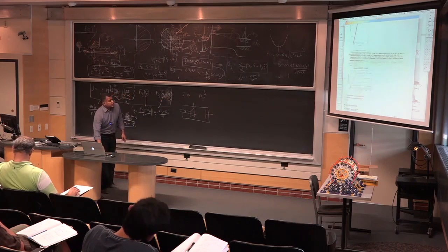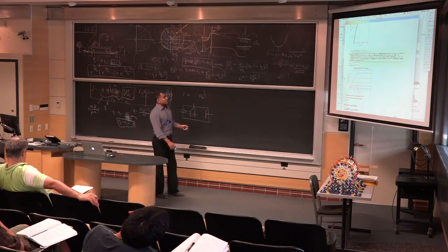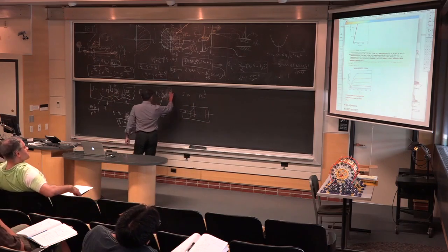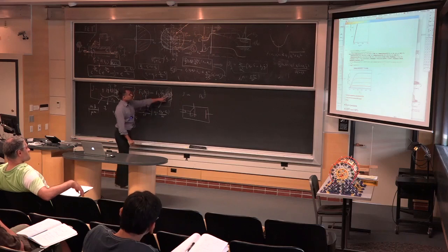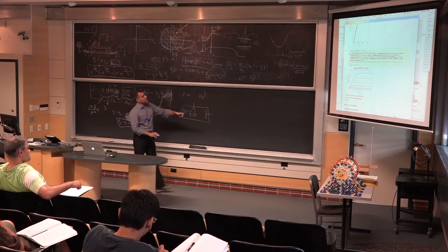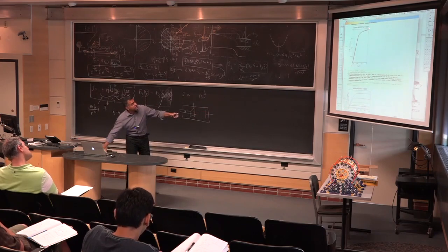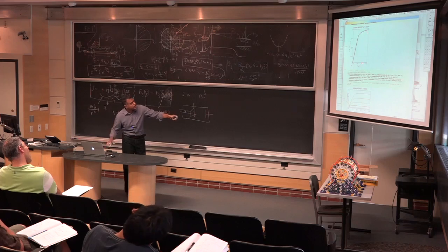And the other very important part of the transistor is when you plot the drain current now as a function of the drain voltage. Right? So now we are changing VDS. For a fixed gate voltage, when VGS is sitting maybe over here, which is on, with a large enough gate voltage, then you get this blue curve on the top.